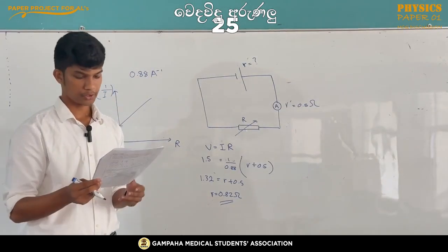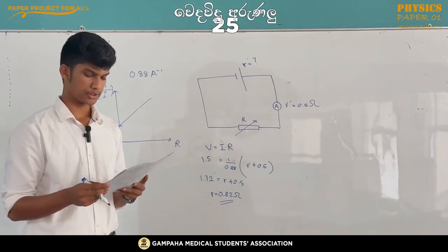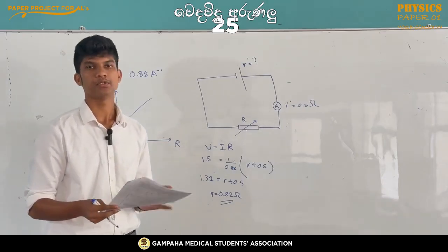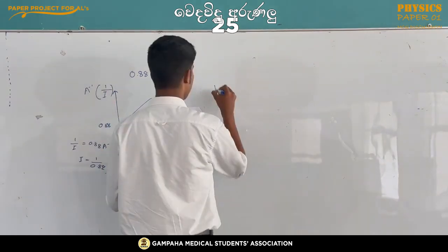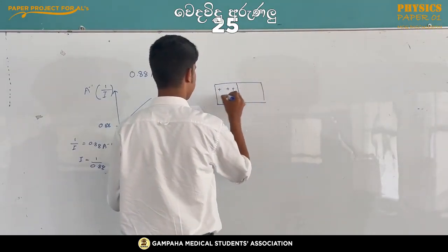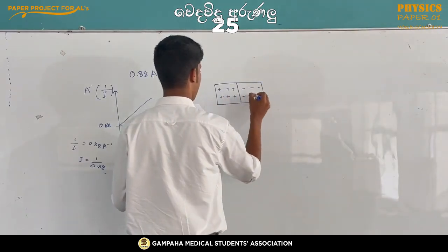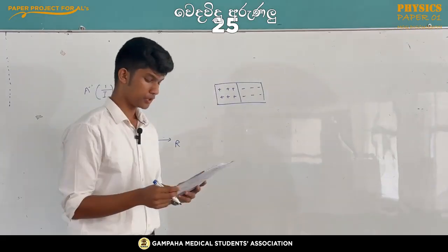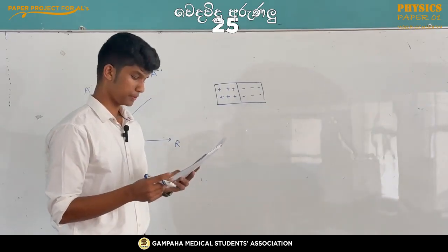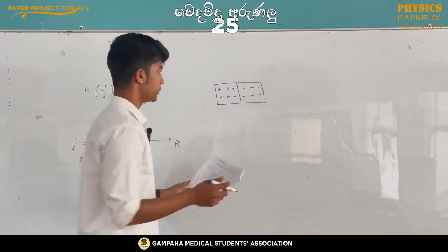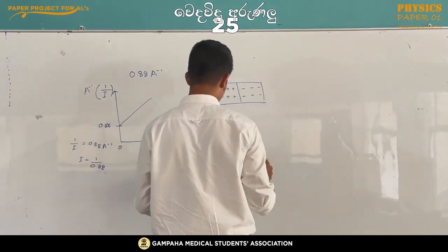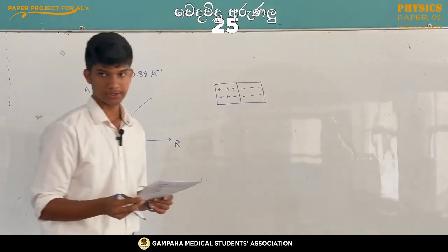In question number 15, which of the following statements are correct? In a PN junction, the positive potential of the internal barrier is located on the N-type semiconductor. This is actually true since the electrons from the N side diffuse to the P side, leaving behind positively charged donor ions on this side. So this side becomes positively charged, and this is a correct statement.